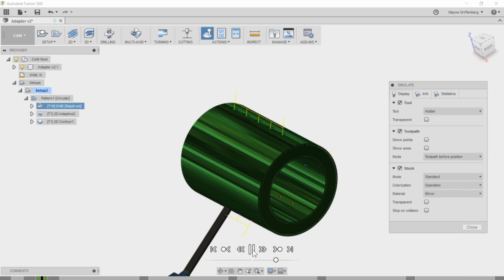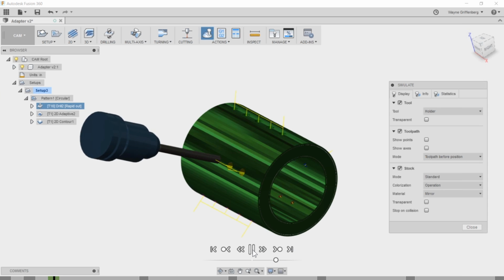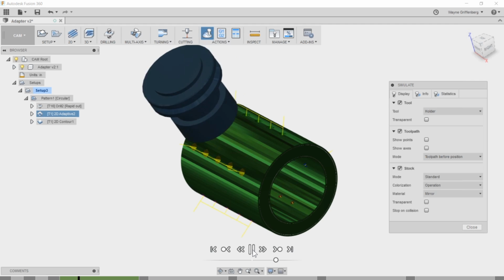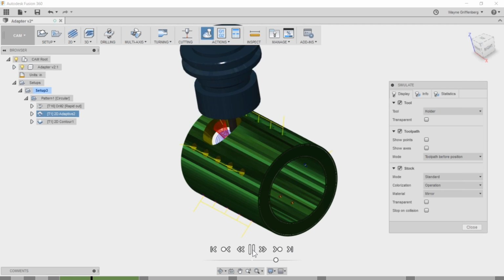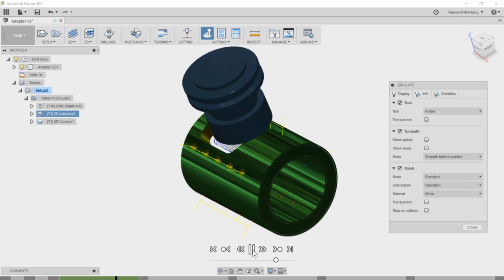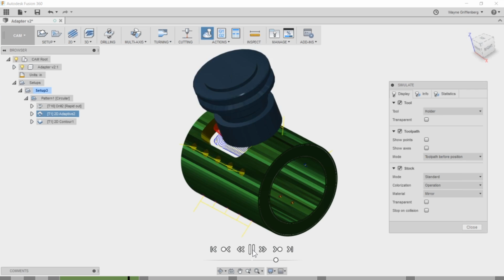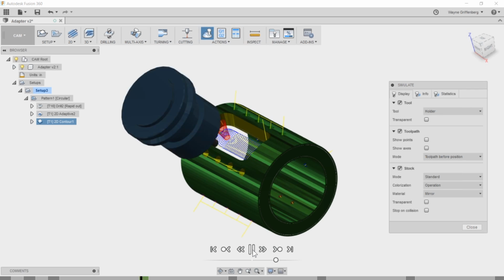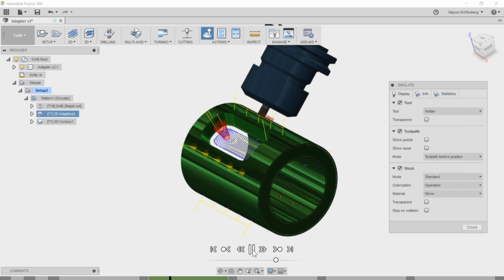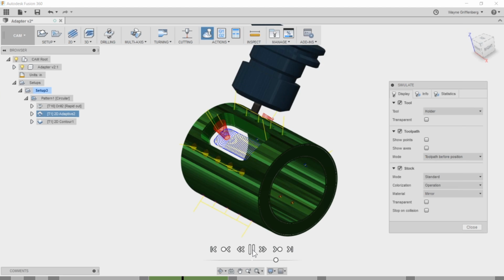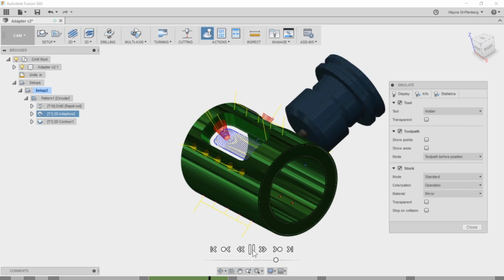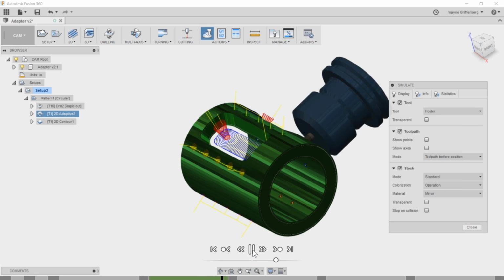While we're answering a couple of questions here, first question: does importing things like Inventor models remove the parametric and smart feature control? If so, with existing Fusion models, can they be updated with a revised external CAD model and retain associativity, or at least maintain the CAM data and prompt the user to reassociate? I think I can answer half of this question. Just correct me if I'm wrong here, Wayne. If you bring an Inventor model or SolidWorks or things like that into Fusion, you do lose a lot of that design intent. Features you're going to lose, but it'll come as what I like to call a dumb solid, like a brick model. Just correct me if I'm wrong here, Wayne.